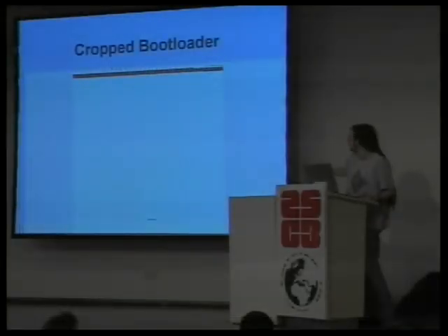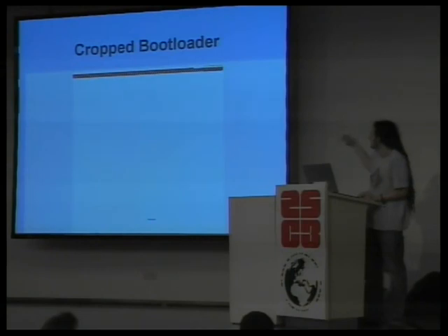You'll note that there's still some blue lower in the image, and that's because blue doesn't refer to data that's actually in the image, but data that's referred to in the image. So the blue band beneath the interrupt vector table is a region of memory pointed to by the proxied IVT.